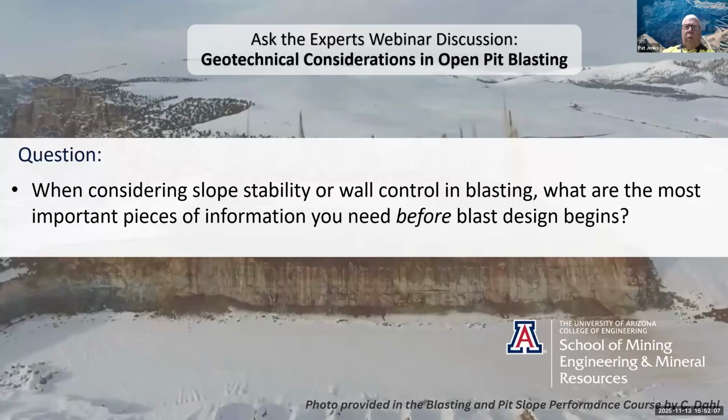Just one other thing to add is that Ray talked about the structure and the rock fabric, smaller scale structures. Another couple of key things we need to make sure we're keeping in mind with respect to slope stability and wall control, as being important before you design the blast, are things like the lithology and the alteration, because that's going to influence that pattern design as well as your product selection.